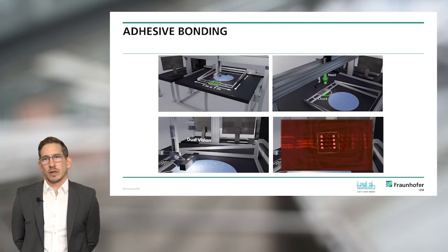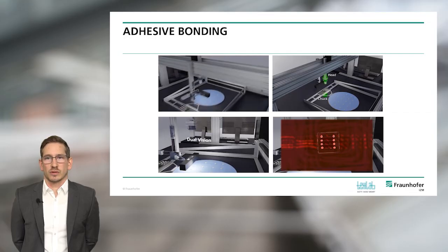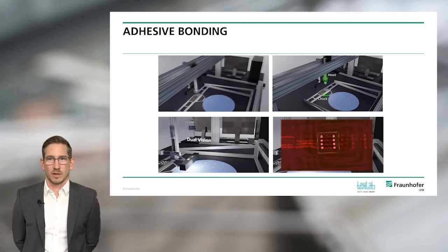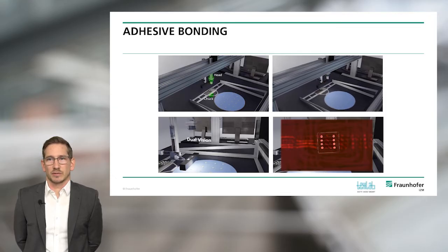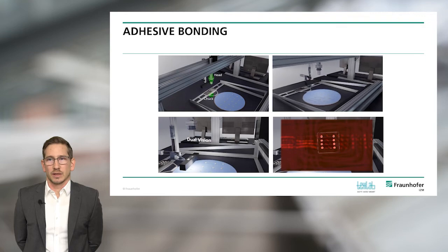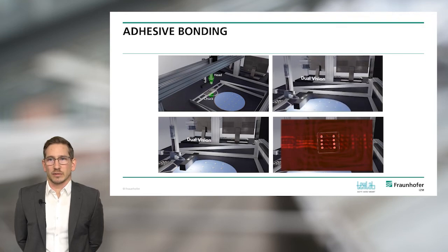In the first step, you can process 1 by 1 meter, and you can use conventional frames that are already used in industrial embroidery machines. These frames can already have the textile circuit inside, and then you can just put this frame into the textile bonding machine. The next step is that this machine picks up an electronic module with a bonding head and then puts the electronic substrates below the bonding head.